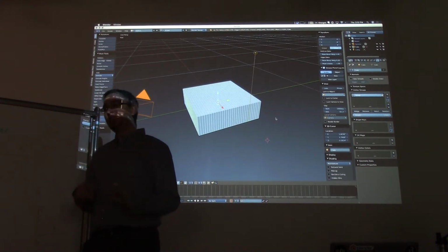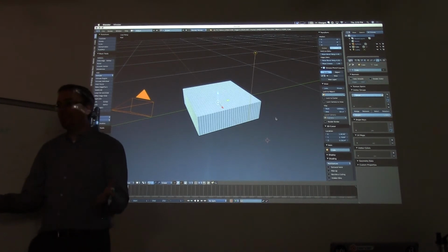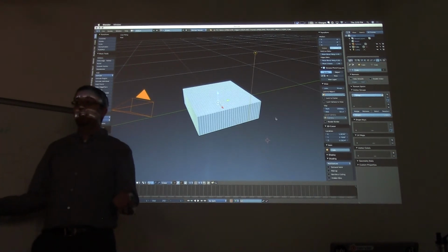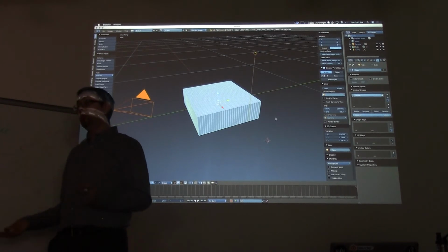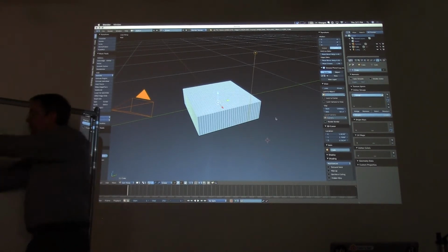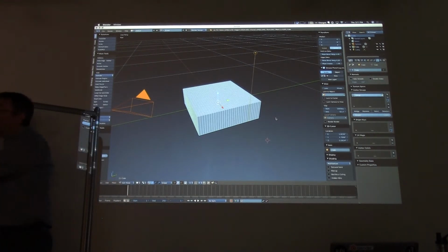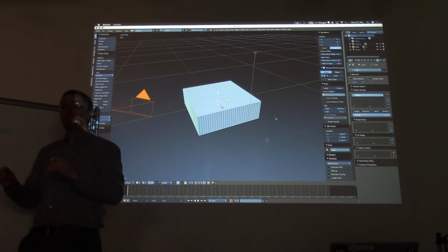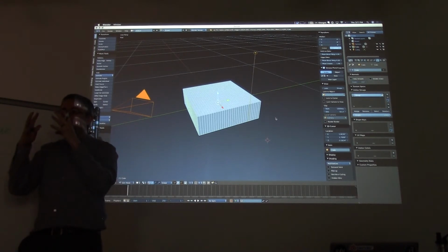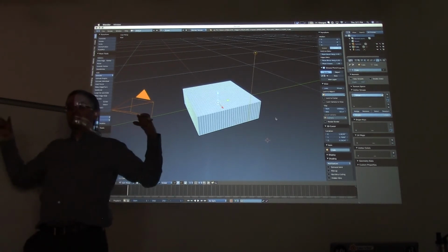I know it sounds crazy, but what Subdivide does is it gives it twice as many faces and rounds everything off. The more extreme it goes, the more you get. So crease basically says, take this edge and put some tension, pull the surface back tight against this edge. By saying crease L edges, we've said, no, you can't deform into a little ball. We're going to yank you back out from every edge to crease you into the corners.